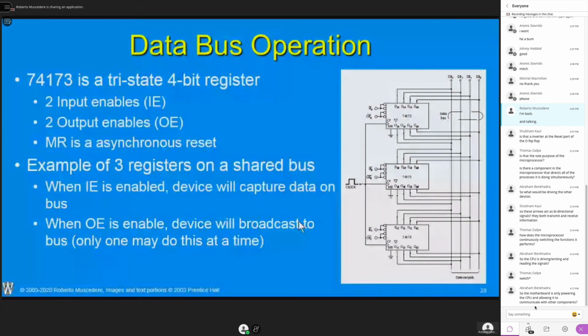So even though all the devices can potentially listen, we typically only command one of them to grab the information. And it does it within that clock time. So again, you can imagine other things on this bus as well. I mean, there could be a CPU or something, but I can't have more than one device talking on the bus, or we get into this situation where we do have a bus contention. And that's essentially, the bit is wrong or the information is wrong. And if the information is wrong, we can expect subsequent operations to be in error. The information is just wrong.